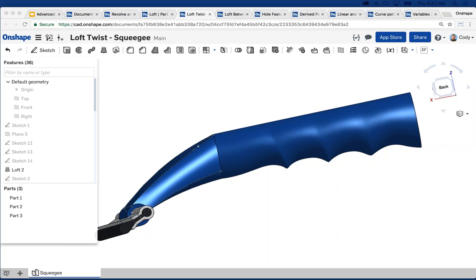Can I use solid edges as guides? Yes, but they would need to be tangent. You would need to have one continuous edge to define that as a guide. So in rare situations, yes. Most often, I would say no. You're probably going to need to construct something. Can I make the spline tangent to the handle? Yes, you could. You can easily attach constraints to the spline handles.